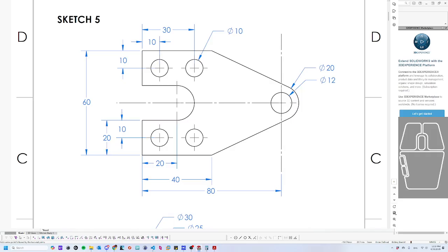And then I'm going to go until the endpoint is vertical with the starting point. Then I hit escape, I click on my line tool, and I go over to the left, up, to the right. You don't have to line these up because you can always line it up later. As long as the general form is correct, you can always add more information, more constraints, more dimensions.